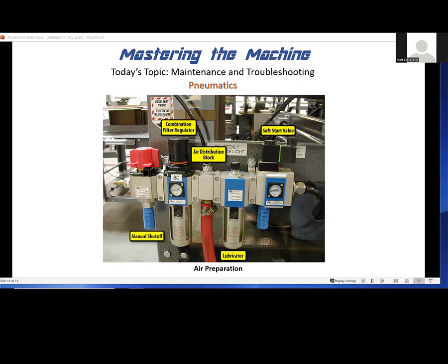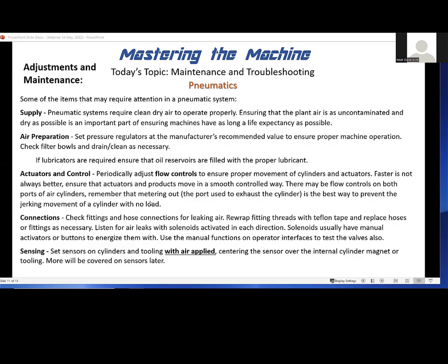And then I actually put some of the valves on the back. What it would do is pressurize a closed chamber and do a simple leak test and just measure the decay. It would close off the box, and then see how long it took for the air to escape from it. So that's a little mechanism that I built years ago.